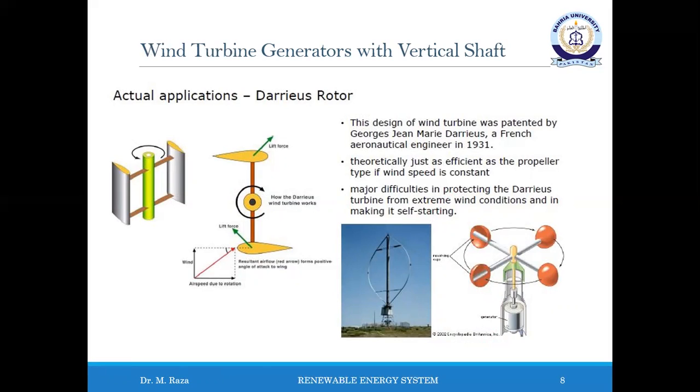In the original version of the Darrieus design, the airfoils are arranged so that they are symmetrical and have zero rigging angle. That is, the angle that the airfoils are set relative to the structure on which they are mounted. This arrangement is equally effective no matter which direction the wind is blowing, in contrast to the conventional type, which must be rotated to face into the wind.